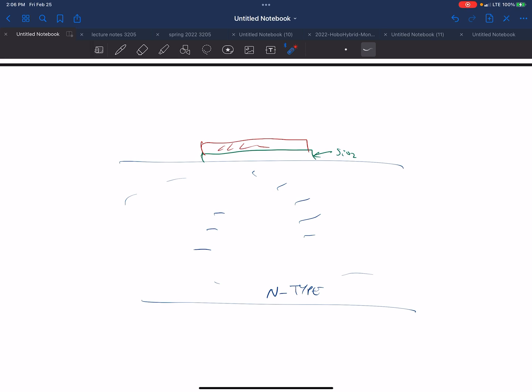Alex, does that make sense? Yeah, so far. Okay. So now I repelled these electrons, and my inverted channel is now positive. But to get a switch here, I need my source and drain. What type of material do I have to put in for a source and a drain for holes? I need to put in P plus layers, because that's where I get holes into my channel.